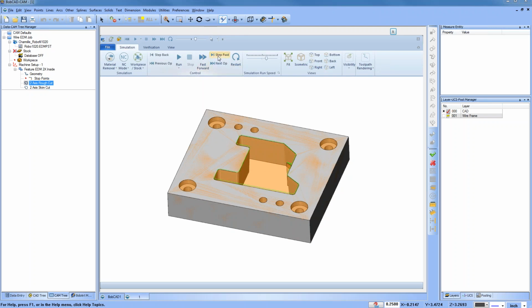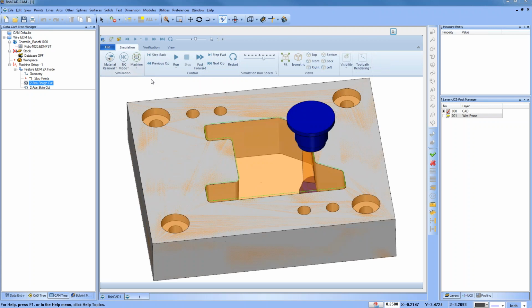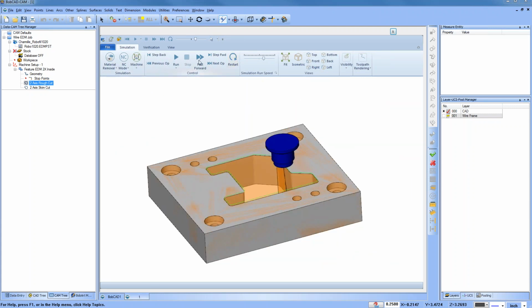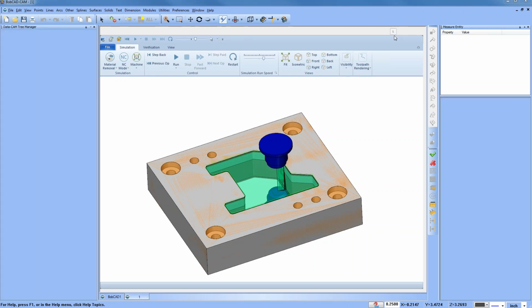You can step through this routine here. If you step through it line by line, you will see where the wire is going. If you have machine simulation, it will show the wire heads. This way you can see where the wire is going and what it's doing, okay? So again, that's just a little bit about simulation. The two key points here is your workpiece is any solid models that are on the screen, and then your stock you can change from show to transparent. And that's really all I want to look at for simulation right now.